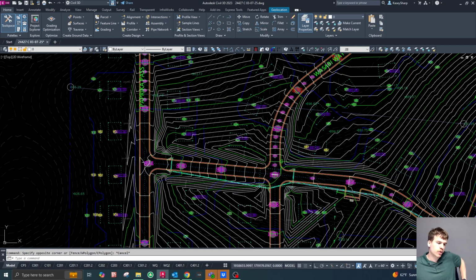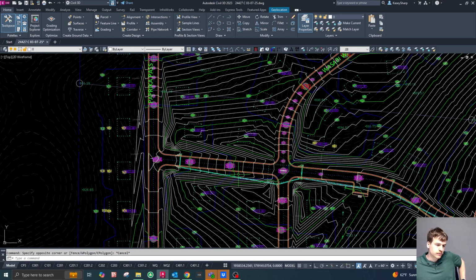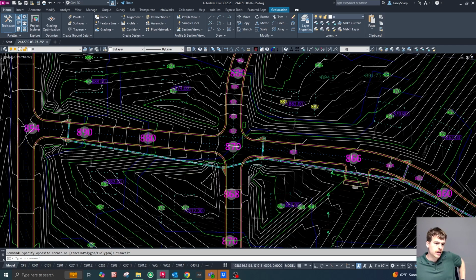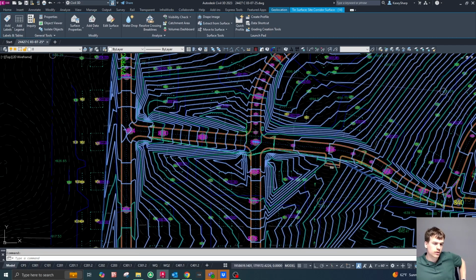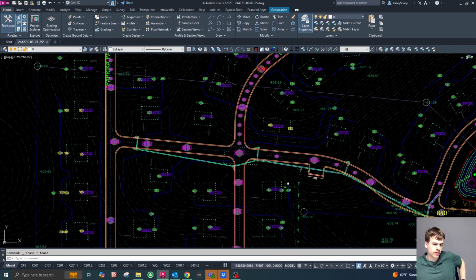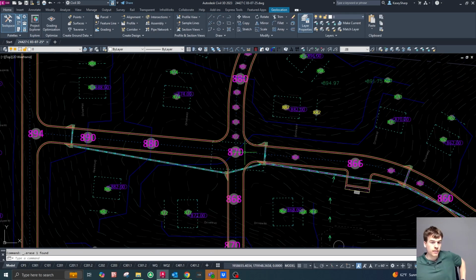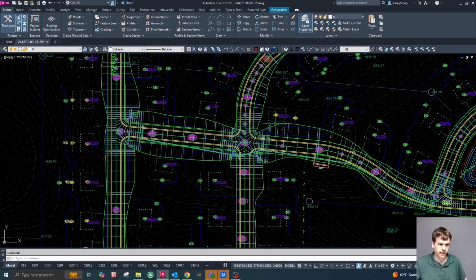When you create your corridor all as one thing and then use the intersections, where the roads intersect, you can just extract one surface, which is this surface here, which will vastly expedite your grading. So I'm going to delete that just because we're not going to keep that for now. That's going to expedite the grading plan, and it's going to make maximal use of the corridor itself. So I'm going to turn the corridor back on one more time so we can take one final look at it.